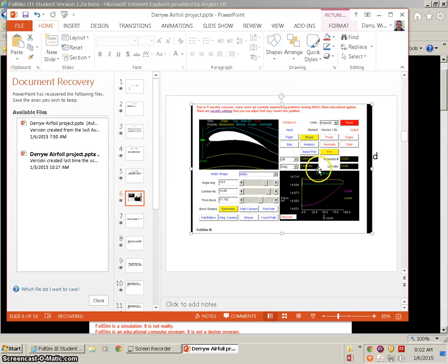I would say that this is probably a little heavy on the drag side, but got quite a bit of lift. I don't know if you've ever flown in an airplane and looked out the window, but at landing time you'll see the wing flaps come out and come down, which creates this large amount of camber, and that allows the airplane to have plenty of lift while it's traveling slower and coming in for a landing.